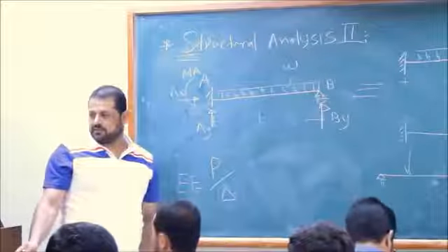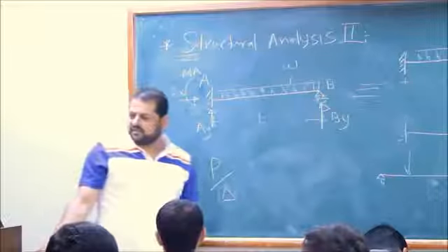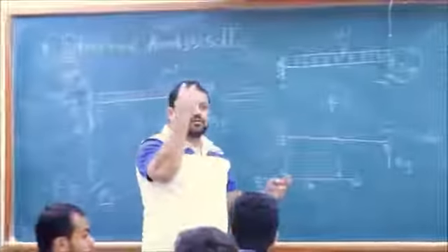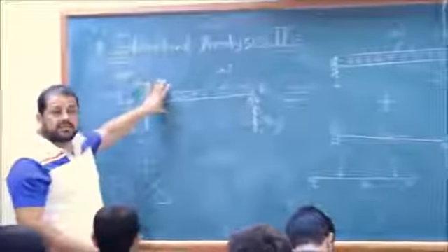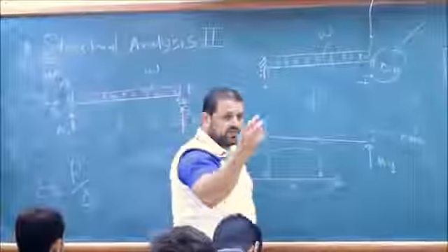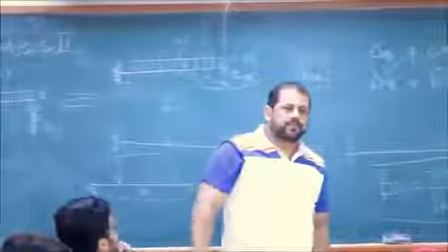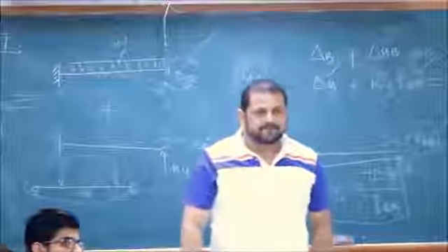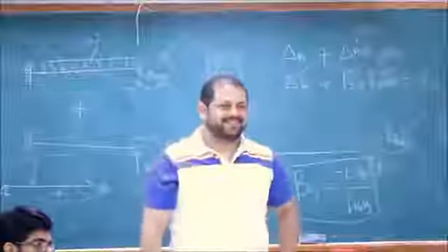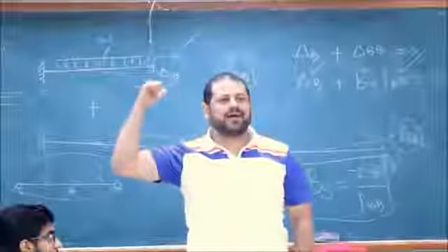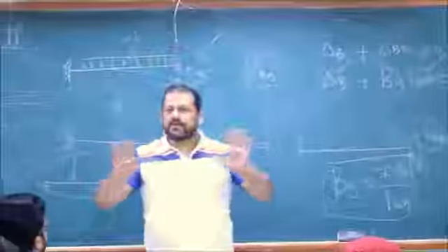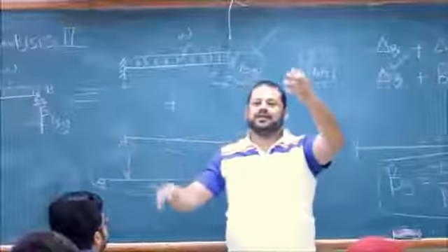Next time we're going to solve two examples, one example like this and one example on this one here. In the next lecture we're going to solve two examples. Question: Doctor, you remove the redundant force to make it determinate, then you add the redundant and apply compatibility to find the force, so that it becomes a procedure? Okay: remove the redundant to make it determinate.